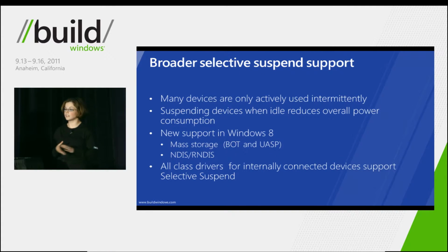Now let's look at Selective Suspend a little bit more. Many devices, such as fingerprint readers or other biometric devices, are only used intermittently. And so suspending such devices reduces the overall power consumption. And it actually allows for the controller to go into lower states and become idle.